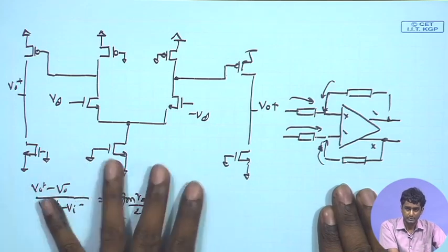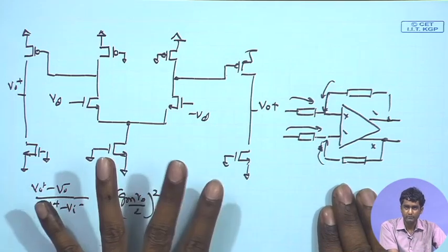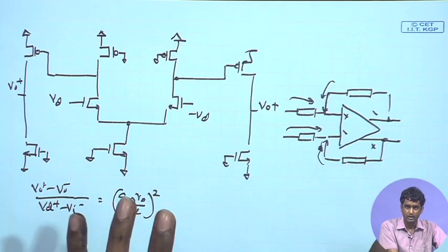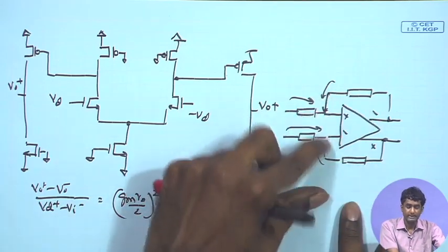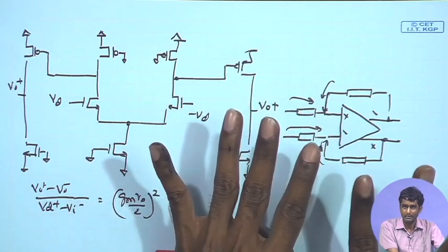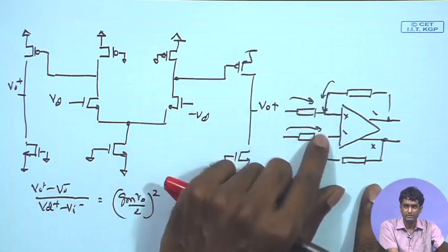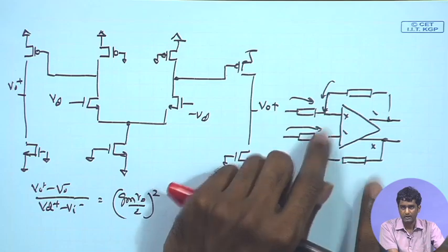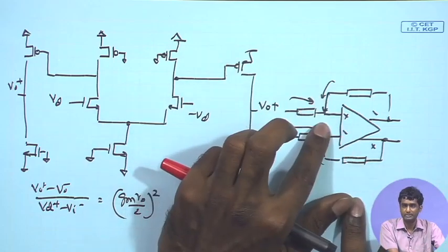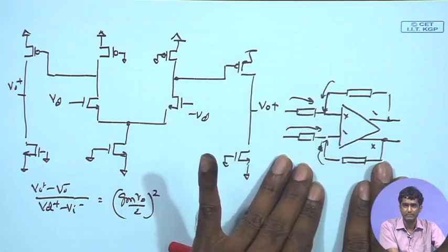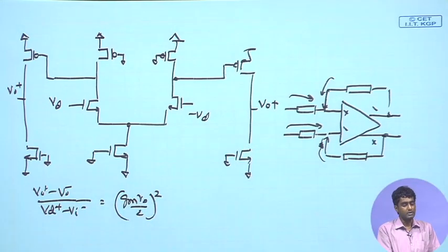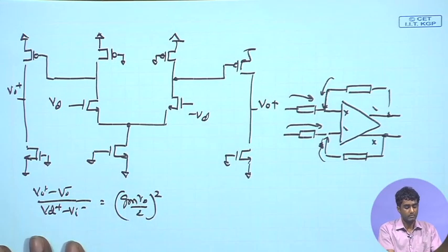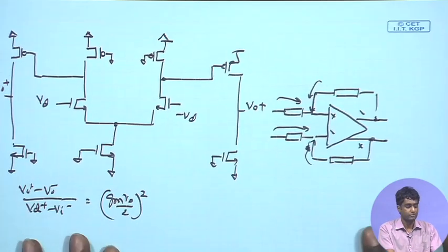The stability of the feedback loop that we are applying for getting a well defined gain, and apart from that, in presence of this feedback loop, whether the DC bias point at the input is satisfied, whether we are having appropriate DC bias at the input, and what can be done to achieve a proper DC bias at the input. So, both these criteria need to be examined with respect to the differential operation also. So, we have done it for the common mode operation. Let us do the same for the differential operation.